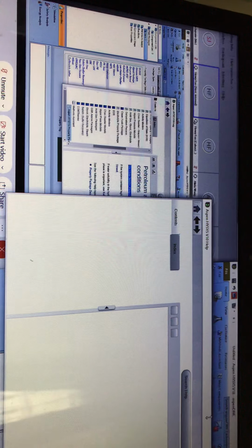In this case, start by selecting all the following options. Maybe specify by component type, and then what type of system do you have? Maybe hydrocarbons, and then you answer the questions yes or no, it's up to you. Once you answer all the questions, the help engine will suggest what type of fluid package is suitable for your case. In this case, they suggest three: Peng-Robinson and SRK. So either one should be fine. You can use either one as your fluid package.